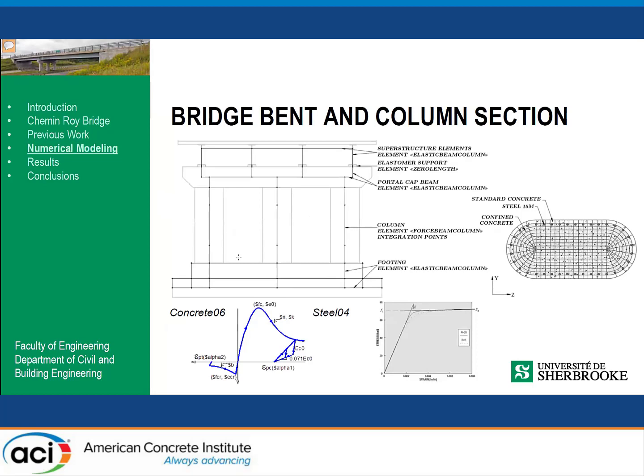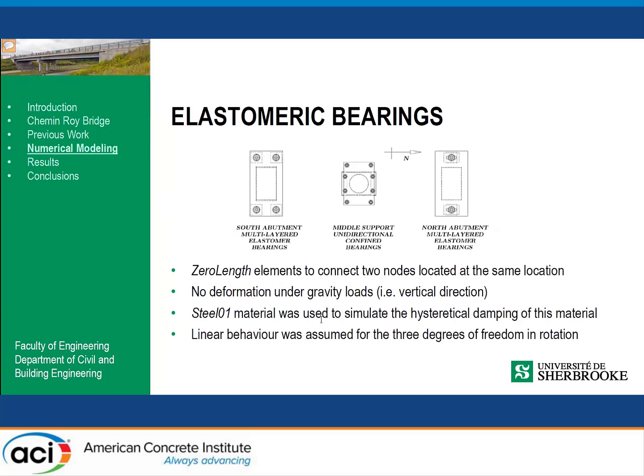In this model, it's a typical bridge. Most of the energy dissipation will take place in the columns, in the plastic zone region at the top and the bottom of the columns. We use the Concrete06 model for the concrete and steel for the reinforcement. So it's quite typical models, really.